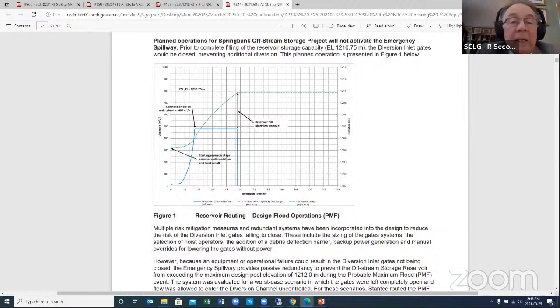Do you agree that a simplified liquefaction triggering analysis can be used to estimate post-seismic deformation induced loss of freeboard of the dam based on the method of Rauch et al. 2007?